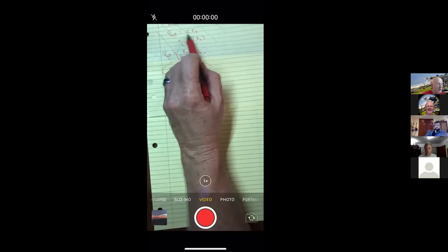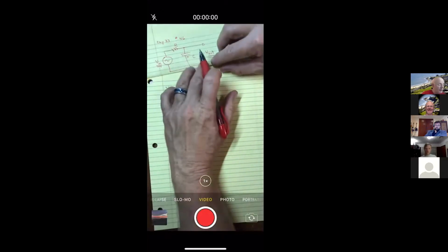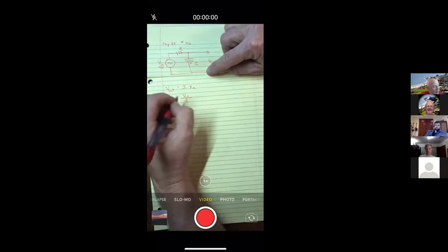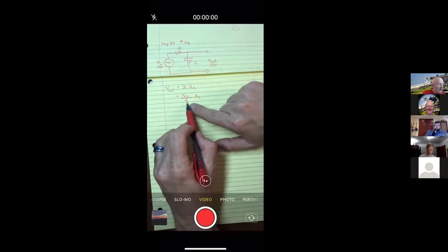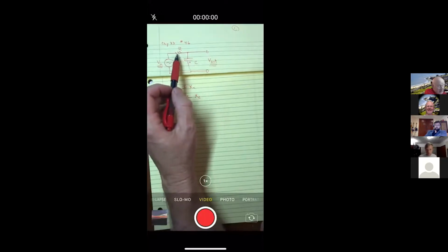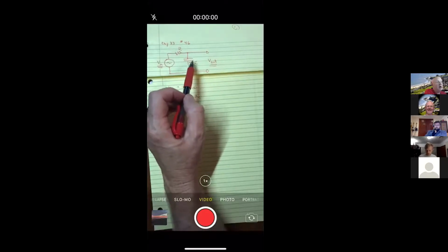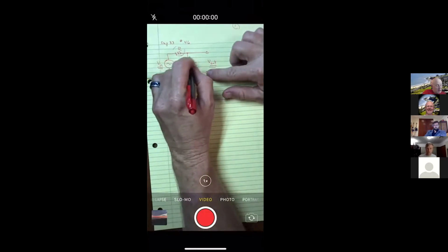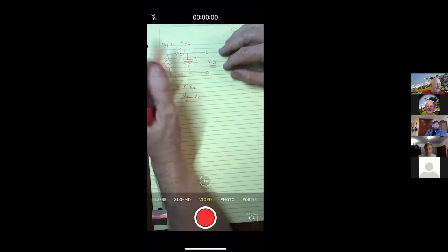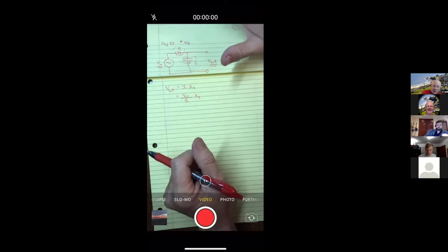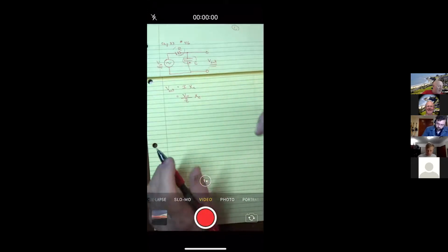Hopefully that's this first step. Then I go on to this next step. Okay, how do I get the current in this circuit? Well, this is where chapter 33 came into play with the AC circuits. You would take the voltage that you're putting in and divide it by, we like to use the word impedance instead of resistance. And of course, we like that because what is opposing the current isn't just resistance, it's also the electrical effect of the charges on the capacitor. So this opposes the current by resistance. This opposes the current by reactance. The two together is called the impedance. And so the total opposition, the combination of the resistors, the capacitors, and the inductors. Now, this problem doesn't have any inductors, but that's the impedance.